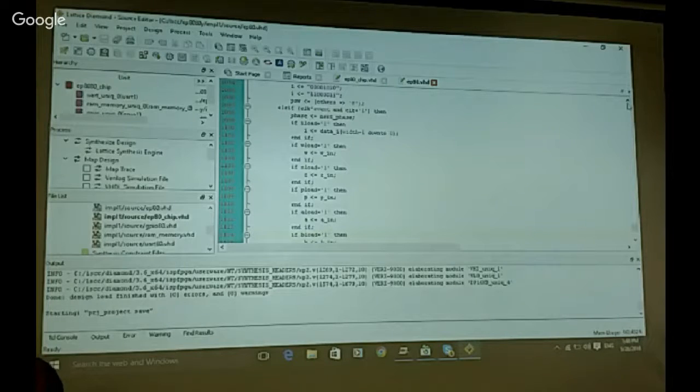Then you get to the finite state machine part. That means on the rising edge of each clock, what happens? If any of the registers has a load signal set to 1, you copy the input to the register, and that's what a CPU is doing.